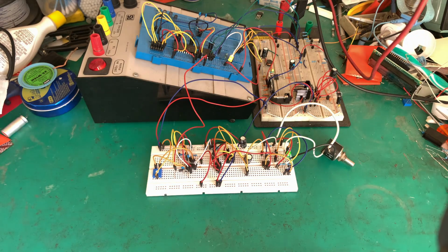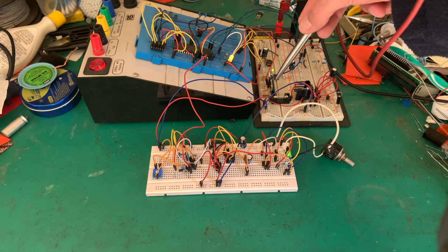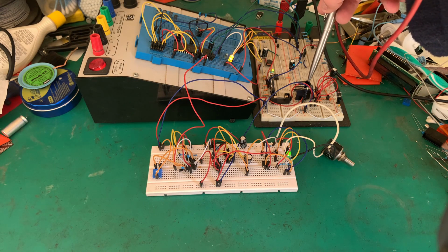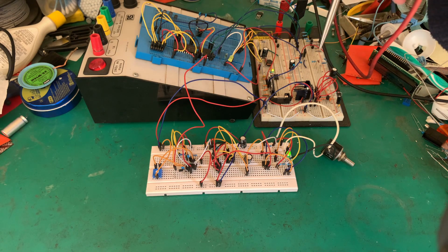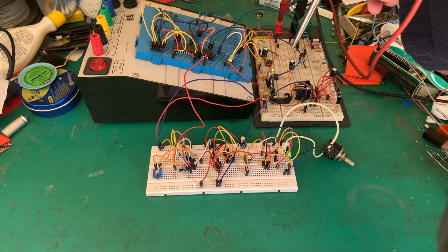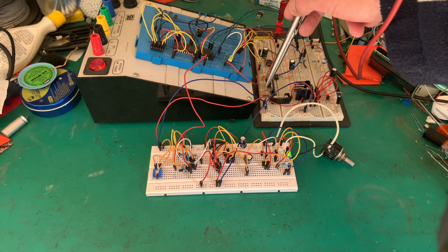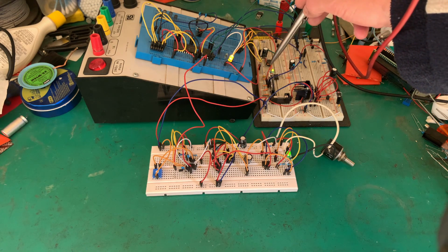Right, so here on the bench, we have a lot of breadboards going on. That's obviously for a reason. We've been testing our different circuitry. Just to recap up here, this is our voltage regulation to take our 56 volts down to 36 with its little series pass transistor, the differential amplifier transistor down here, our short circuit protection there with our SCR. Jumping across to there, our little switching circuit to give us our 15 volt rail up here. Our 15 volt rail, we go through our different regulators, our 12, 5 and 3.3.